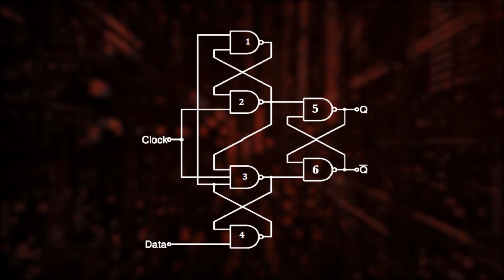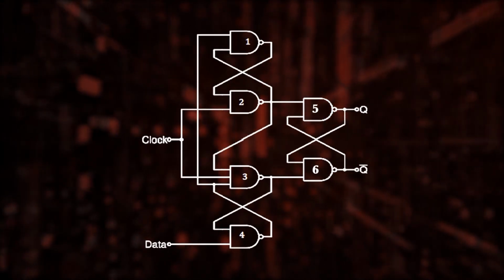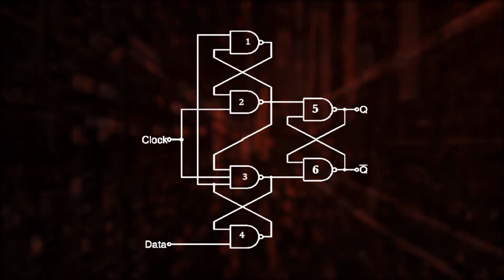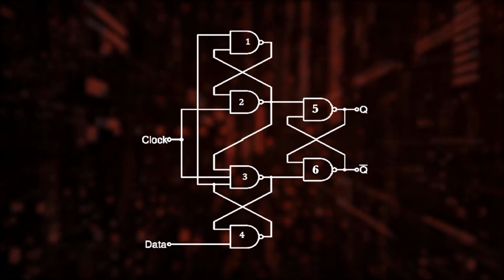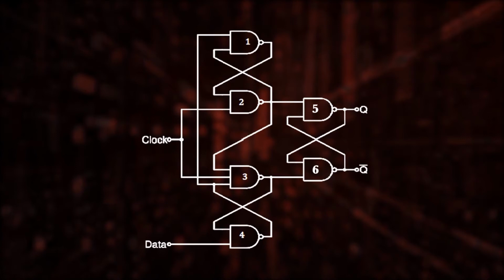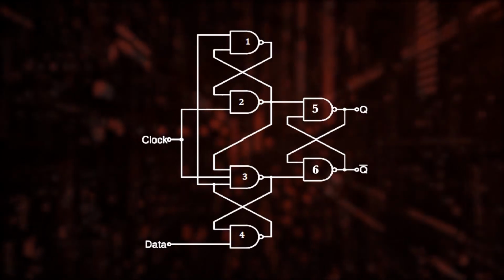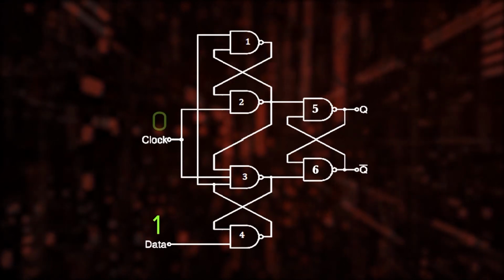Now, the clock pulse will be turning back to 0. You can guess the state of the flip-flop. It will set the inputs of the SR latch to 1 again and will continue to remain in the previous state itself. At this state, now the flip-flop's input is changed. That is, D equal to 1. Now, the clock pulse is still 0.